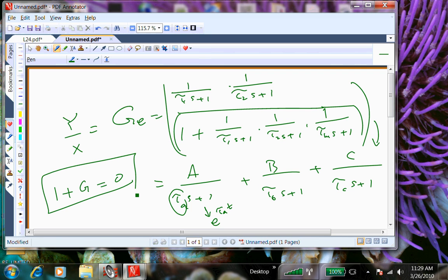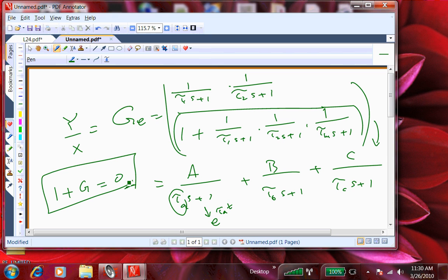And one aspect of controller design is to make sure that as you are changing KC, tau I and tau D, you always keep the 3 roots in the left half plane. So there is a method called the root locus method that we are going to see. Okay? The basic idea there is, as I change KC, how do these eigenvalues move? Is there a value of KC where the eigenvalue will cross to the right half plane, become positive?